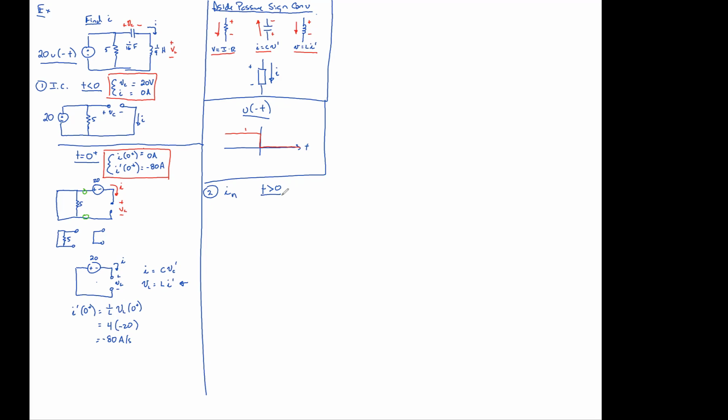Well, let's see. Is it? What's the voltage source? It's a short. It is definitely a short. And by the same reasoning, do we need to draw the 5 ohm? No, because it simplifies. It can combine with that short, and since we don't need to find voltages or currents through it, that makes it simpler.